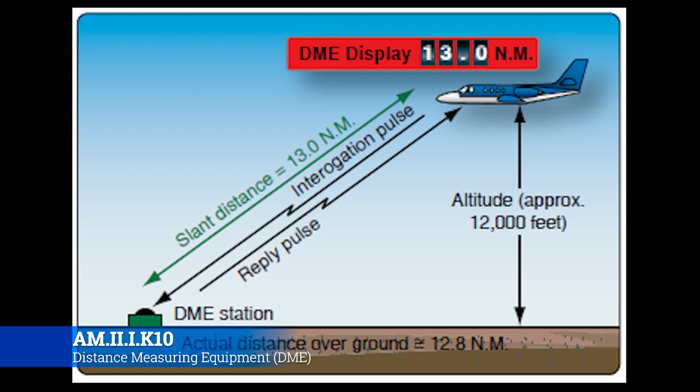You can say, hey, look, I am at this bearing at this range, therefore I have to be there. You throw another VOR DME station in, and you're going to know exactly where you're at, because it's unlikely that both of them are wrong in the same ways. So you should be able to plot that on the map, then look out the window and see the mountain that you're trying to avoid, or whatever, and just use general pilotage as a check.